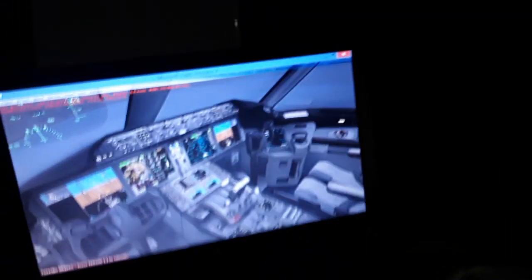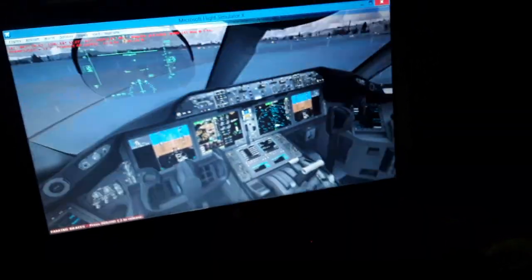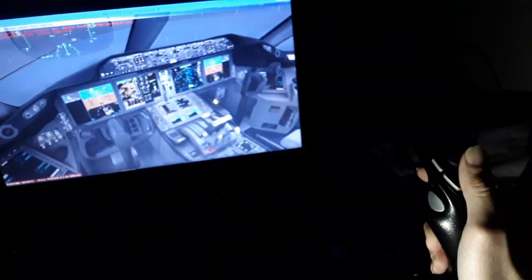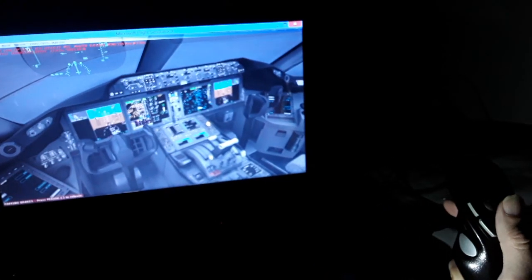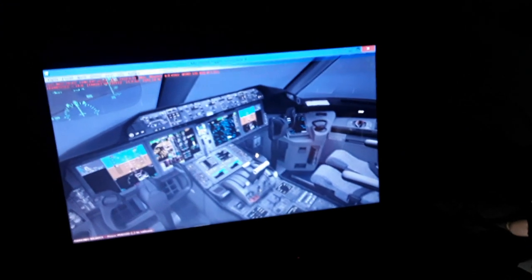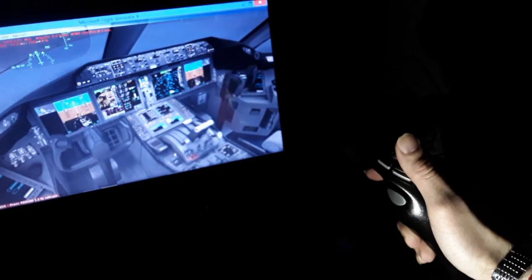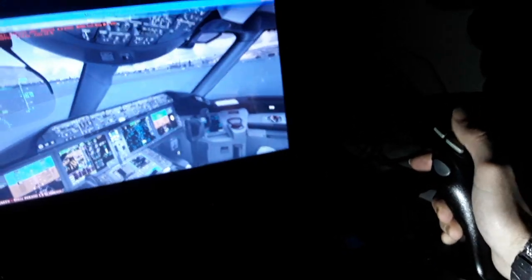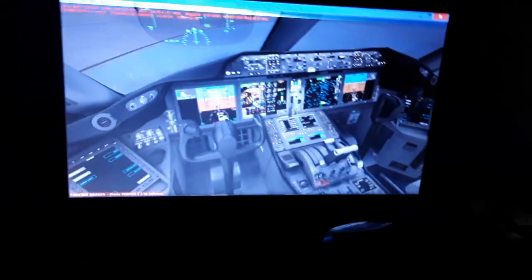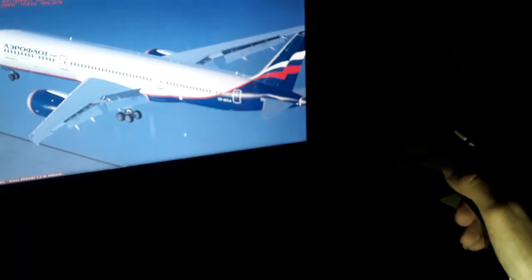So you can see the captain and the first officer are interconnected in flight and move together. The side stick deflection is proportional to the yoke deflection, like this. Climb or descend, make turns. Side stick deflection proportional to the yoke also. They are interconnected, move together, unless we have a failure, and not like in the Airbus where we have side stick priorities. So you can see also the outside view over here, again for using the flight controls,